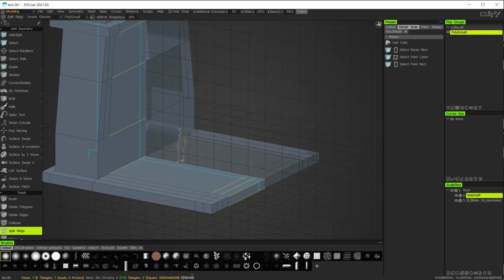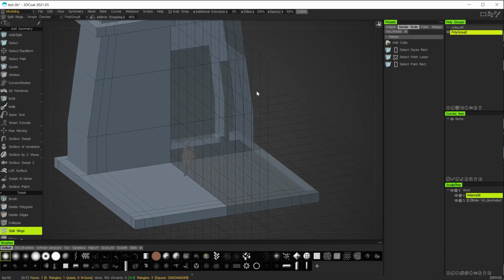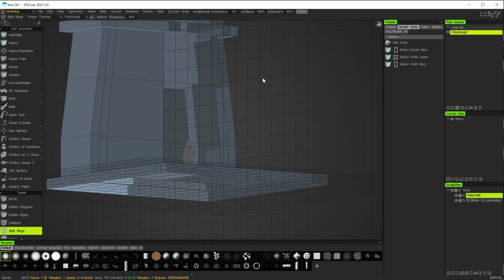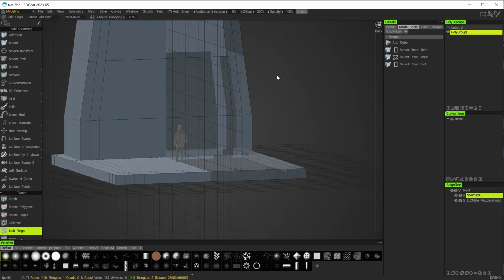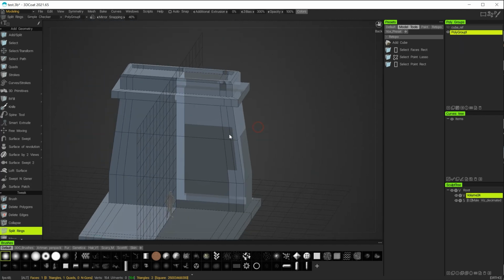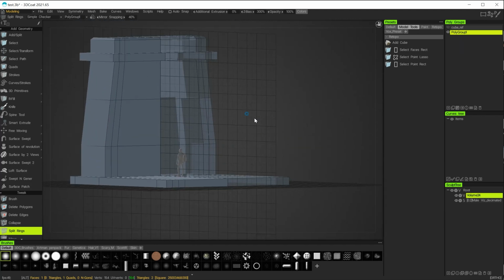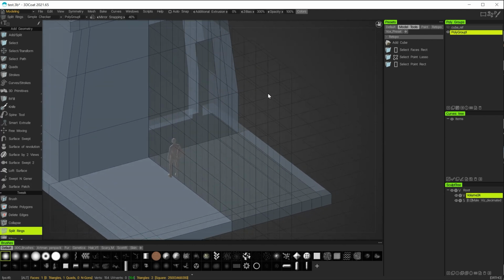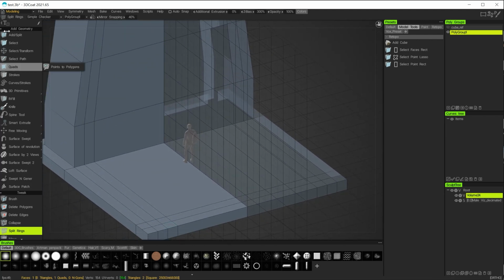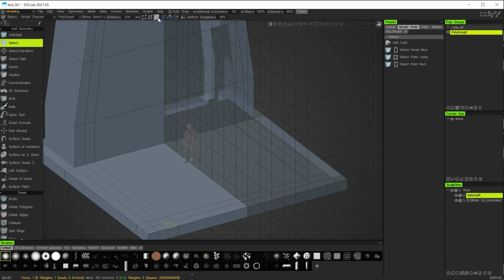Okay. Yeah, sometimes you get those. I was just worried there because I just noticed that it wasn't cut, but actually it was. So yep, that's fine. That gives me what I'm after. So let's extrude these faces here. So let me go over to select faces, and I'll take this one and this one, deselect this one.